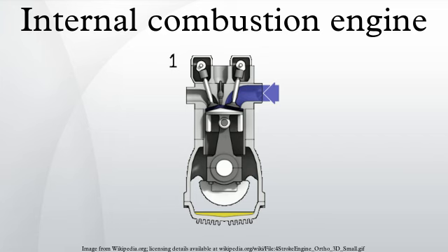Two-stroke engines are widely used in snowmobiles, lawnmowers, string trimmers, chainsaws, jet skis, mopeds, outboard motors, and many motorcycles. Two-stroke engines have the advantage of an increased specific power ratio, typically around 1.5 times that of a typical four-stroke engine. The largest internal combustion engines in the world are two-stroke diesels, used in some locomotives and large ships. They use forced induction to scavenge the cylinders.